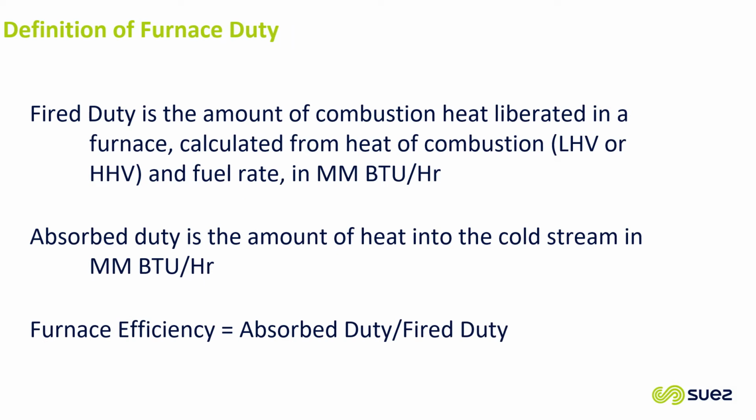There's a slightly different definition that we want to touch on. It's a bit confusing, so we thought I'd put it out here at the beginning, and that's furnace duty. So you'll hear these terms bandied about, whether it's furnace duty or heat exchanger duty, and we think you need to know the difference. Furnace duty, or fire duty, is the amount of combustion heat liberated in the furnace, calculated from the value of the fuel gas that's put in.